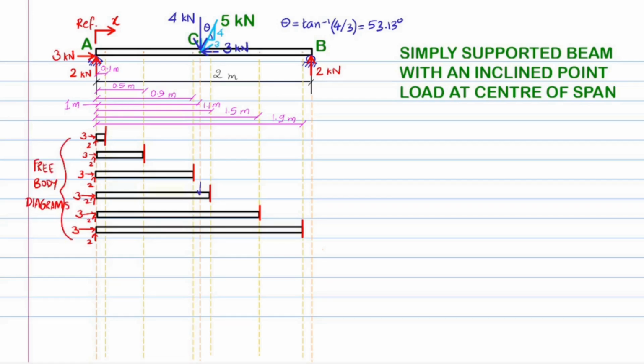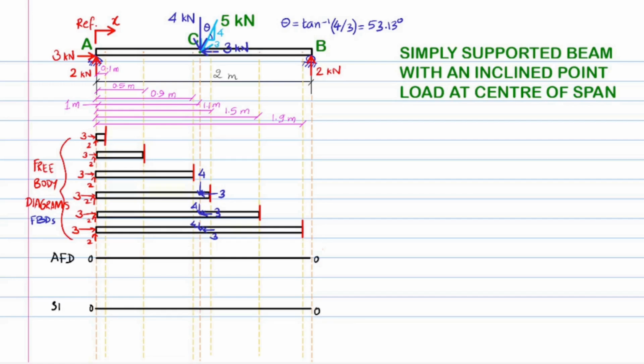We shall virtually throw away the right part created in each case by virtue of the section. We show the axial force, shear force and bending moment in the part created by the first section and plot the values of the same below respectively for each of the parameters. The axial force is the same in value as the reaction horizontal force to maintain static equilibrium, and the combined effect is to compress the part.